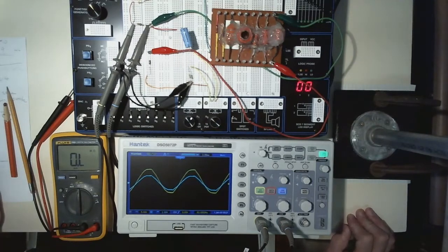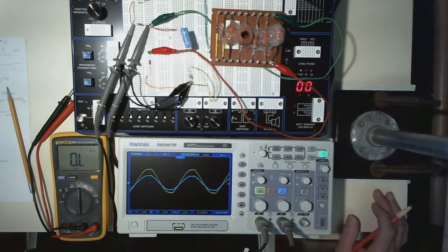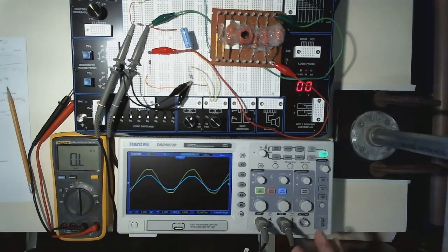But when you fire up the oscilloscope, a few things, it actually has an internal calibration area right here. Maybe I'll point with the old red pin here. You can hook this up and you can calibrate the probes. Usually if you go into a lab setting like we'd normally be in, they don't want you messing with the calibration there. They've got them set up. You leave the probes with the oscilloscope and everything is set. But just pointing that out as you maybe think about going in and starting to use an oscilloscope on your own.